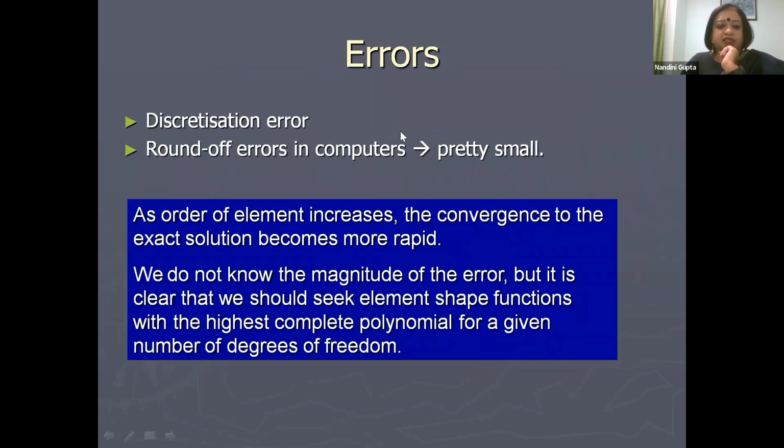So what are the errors that you have? You have discretization error, which I have just discussed, because you are approximating a function with a lower order function. And you have roundoff errors in computers. Well, this was a concern when finite element first came into the picture when we were working in the 70s or 80s. But nowadays, with the kind of computers you use, you really don't have to bother about the roundoff errors.